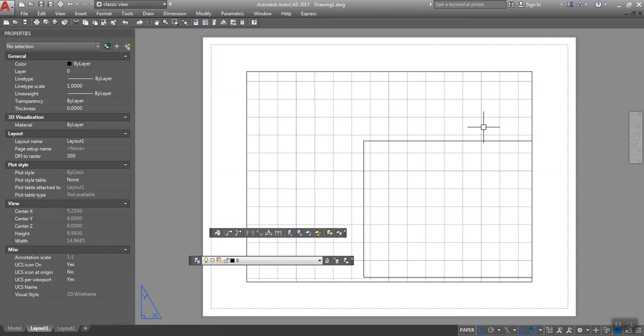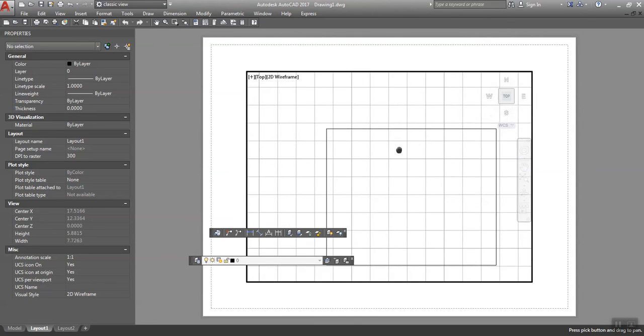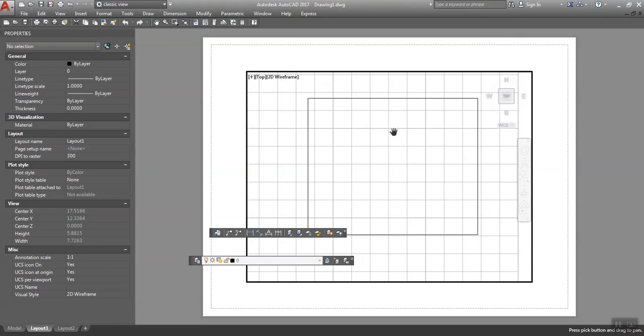Now, how to get into this rectangle that's on the paper space is your plot plan. And so you can either hide it, which I won't get into, but in this space, in this large rectangle you have, in order to move or zoom to see more of this rectangle that we just drew on model space, you got to click inside the paper space. So just double click, and now you are on the model space page within the paper space, if that makes any sense. So I'm going to pan, and as you can see, now we're able to move.